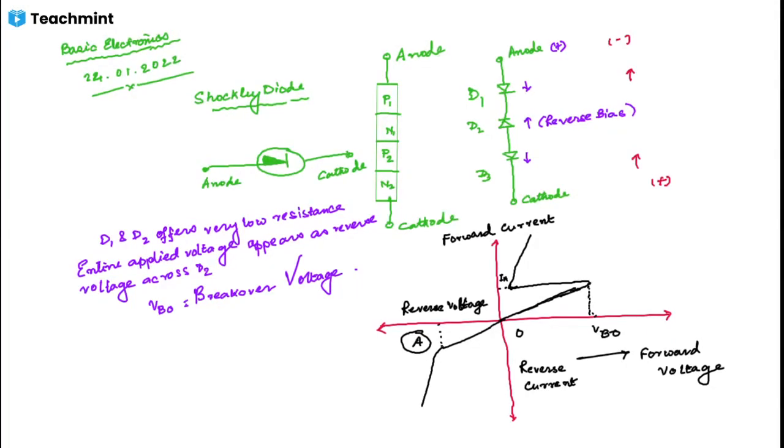At this point, diodes D1 and D3 would go into reverse voltage breakdown. The reverse current flowing through them will rise rapidly and the heat produced by the current flow could ruin the entire device. For this reason, the Shockley diode should never be operated with reverse voltage sufficient to reach the reverse voltage breakdown point.